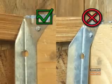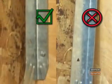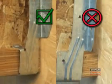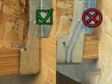Do make sure with top flange hangers that the hanger is plumb to the header and not kicked out. This means that the part of the hanger that sits against the header must be in contact with the header throughout the full height of the hanger. If the hanger is kicked out, push it back against the header until it's plumb, and fill the triangular, optional face holes to secure the hanger in position. Note that you cannot fix a kicked out hanger if the joist nails are installed.